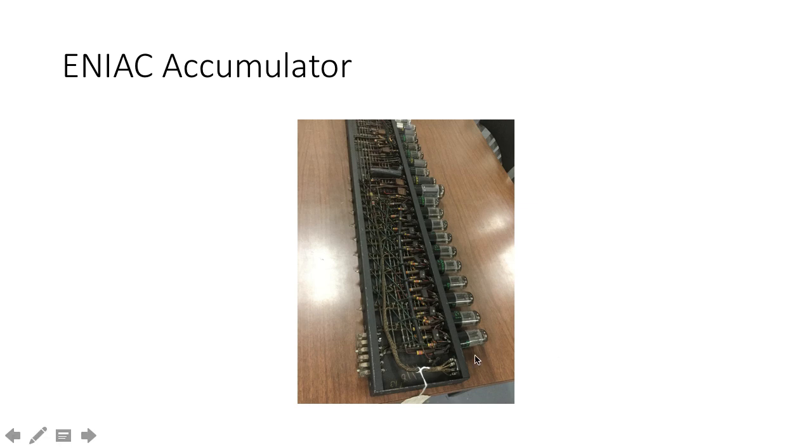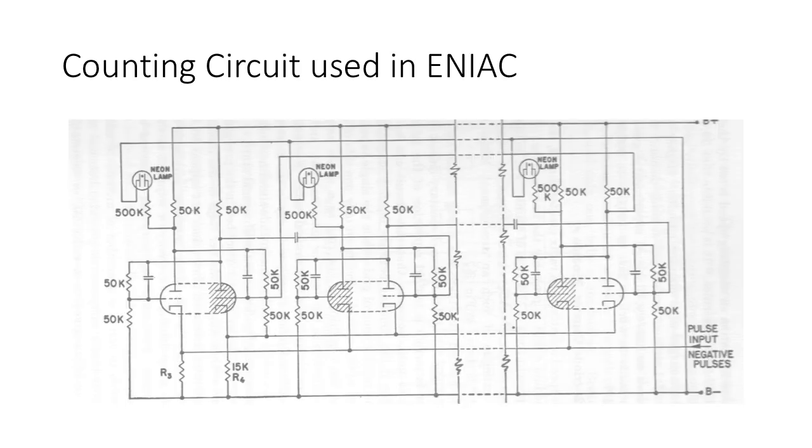full-blown ENIAC accumulator. This is 27 tubes, and there's a wide variety of tubes available. There are tubes for cycling the ring when the accumulator is used for transmitting a number, for adding or subtracting. There are gates for receiving pulses when the accumulator is receiving. There are 4 tubes for pulse standardization and driver tubes to drive the ring on any operation. There's a gate for control and carry initiation.